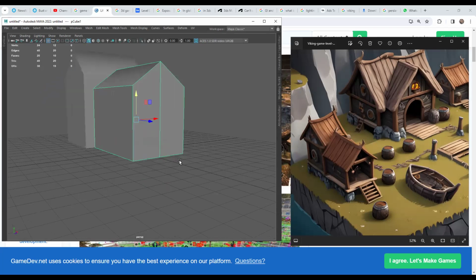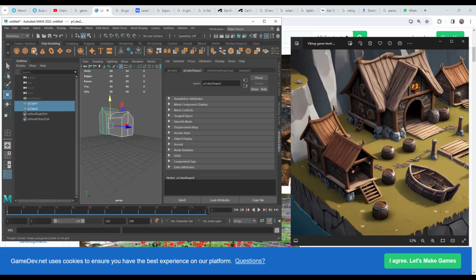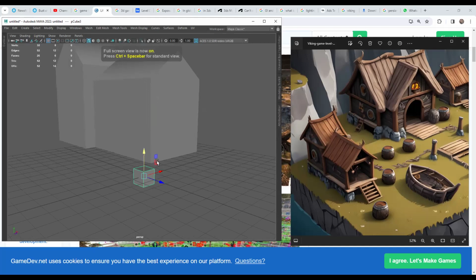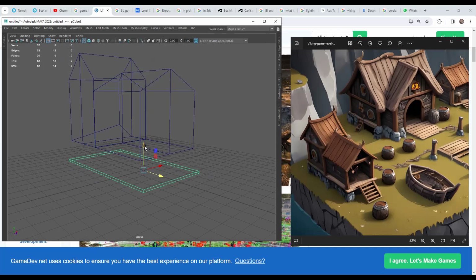Okay. And bottom, create a box again. Scale in top view, with wireframe on more. Only scale the particular axis, or select these vertices and move. Okay, over here these both are the same, so I want to scale it, the breadth and, okay, this one should go up.